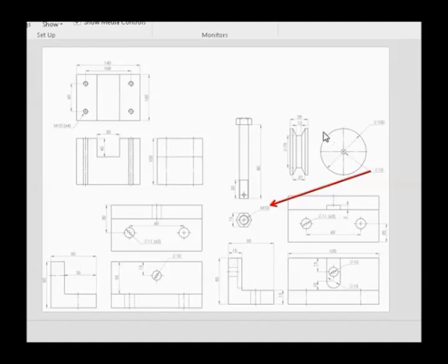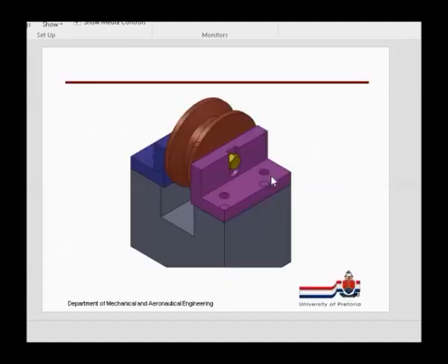The wheel had a diameter of 10 on the inside, width of 39. Now you'll remember earlier when I said the width between this plate and that plate is 40, we can now see that the wheel width of 39 would fit in there, but it would have a 1 millimeter clearance. Usually we like those clearances because a small clearance means that the two plates on the side, the L plates, won't cause excessive friction on the wheel from the sides, so that the wheel can move freely.